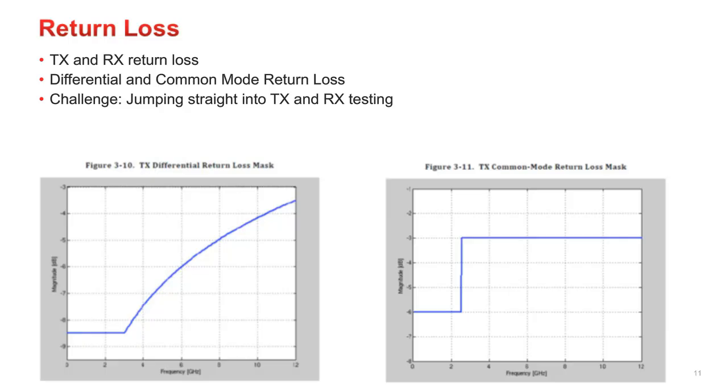So I mentioned earlier LTSSM. It does exist in USB4, but it's not done through the TX-RX lanes. On USB, the sideband pins of the Type-C connector were not used. They are required in USB4. And so the negotiation, the back channel, is done over the sideband. So you need to be able to look at both the sideband signals in parallel with the high-speed lanes when you're doing the link training and link optimization.